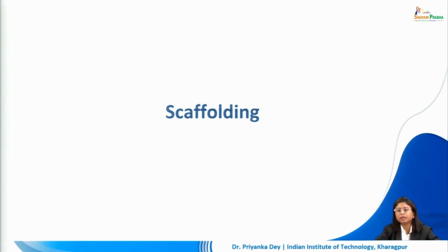So shorings are temporary structures which are used to give support to a temporarily weak wall or a wall which needs some form of opening or alteration to be made. So there were 3 types we studied. We first started with raking shores, followed by flying shores which do not take support from the ground, and the last type was the dead or the vertical shores.